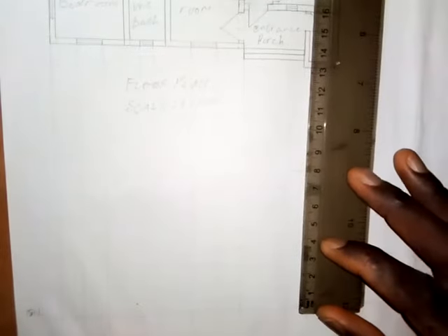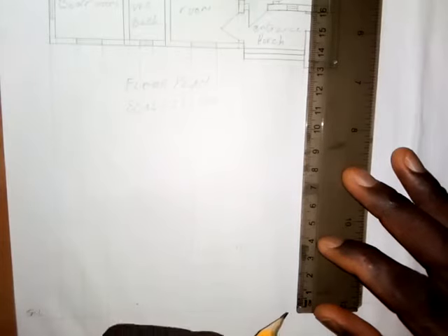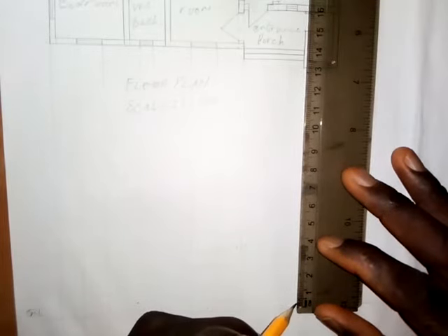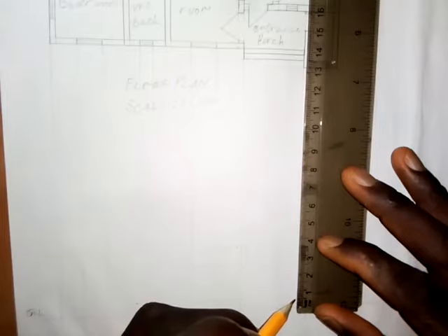So in the specifications, I said that we are making use of the riser, and the riser is 150 millimeters. So 150 divided by 100 will give us 1.5, so we can make it 2 millimeters. This is the distance from here to here for the steps, and we have 2 steps there. So we just take 2 millimeters here, and then I take another 2 millimeters. So this is it. Then I will draw a horizontal line.